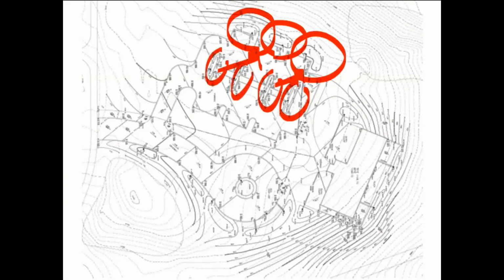All of your paved areas are going to need some sort of a system to capture the water. On the other side, you're going to have to come down past the drop-off area. And then one of the things that we are going to have to discuss in greater detail later is how we do these bioretention systems that are located next to a hill, because this hill is going to be pushing water into the bioretention systems. So we're going to have to create an intercepting swale there. The plan that I'm showing you does not have that. One of the things that's incorrect about this plan that I want to point out to you.